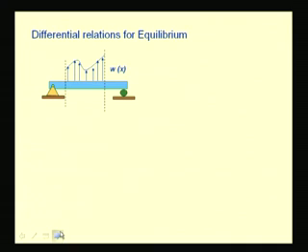For the distributed force, if we consider the differential relations of equilibrium rather than the algebraic relations of equilibrium, the construction of shear force and bending moment diagrams becomes easier. So, let us formulate the equilibrium of a portion of a beam subjected to a distributed load.